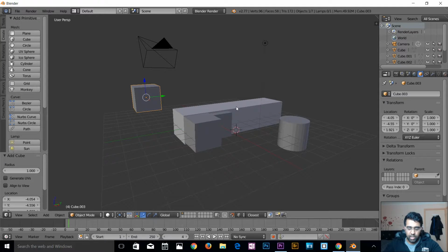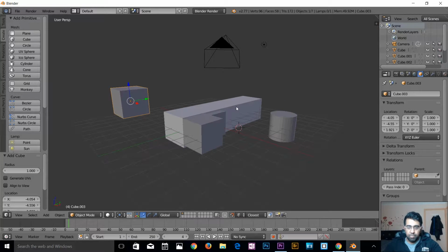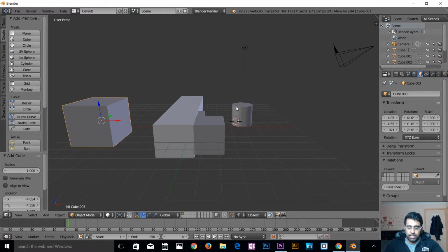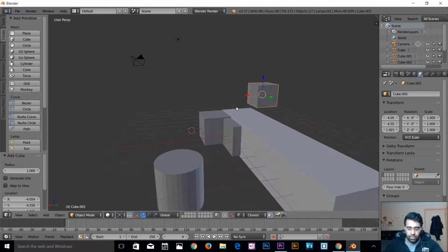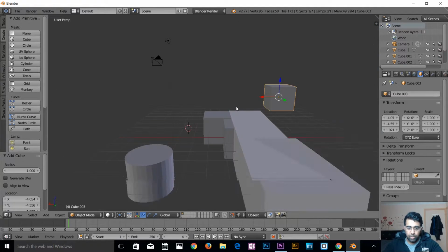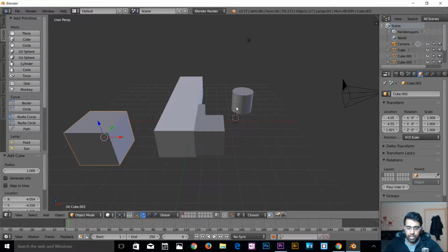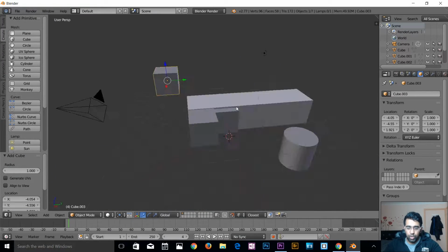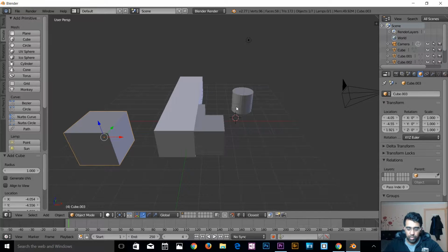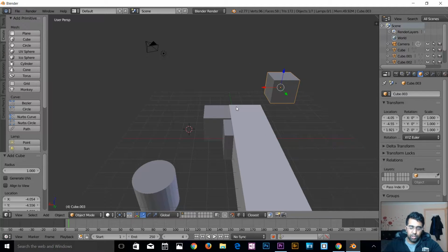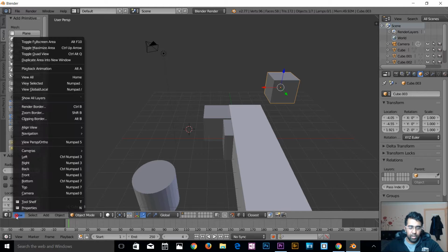One press orbits a little bit, then press one more time, and one more time. 6 will orbit to the right, 2 orbits down, 8 orbits up. And this is going to give us the opposite orbit, 9. So you can go to the opposite view, which is really cool. If you get used to these keys, they are very helpful, but I would still prefer to get a mouse with a wheel. Nowadays every mouse comes with a wheel, just letting you guys know.